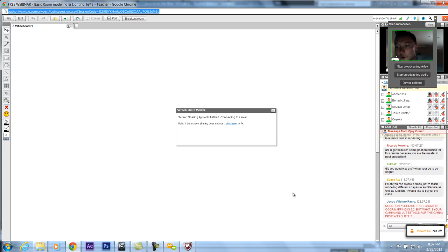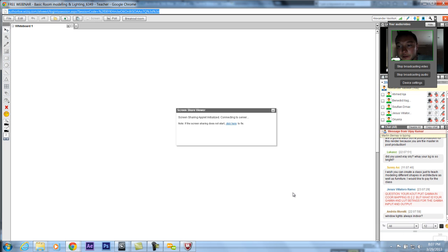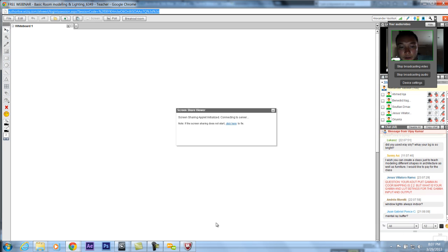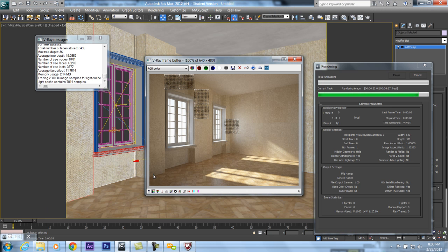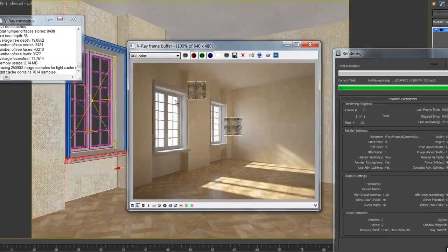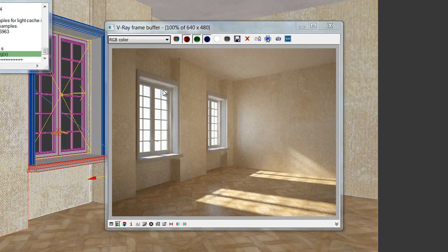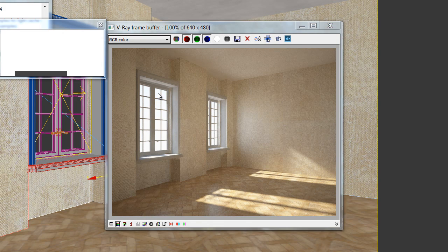Yes, of course. I have VRay Sky in my background. Here you see it's a little bit bluish. I'm pressing a right click on the mouse and I'm getting this table of color content.